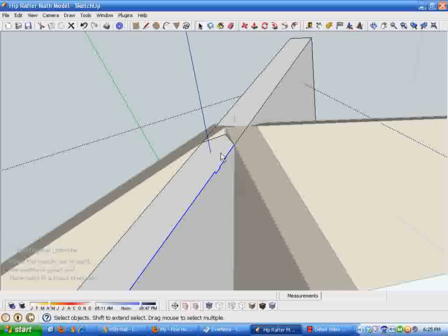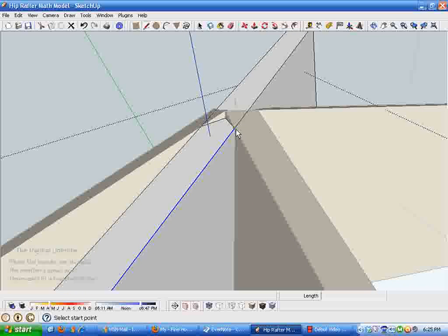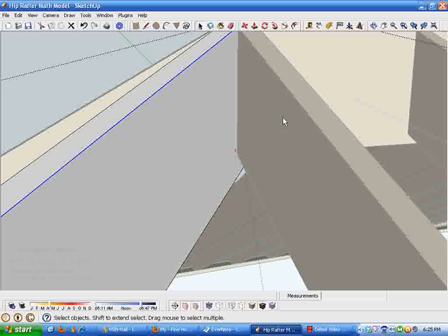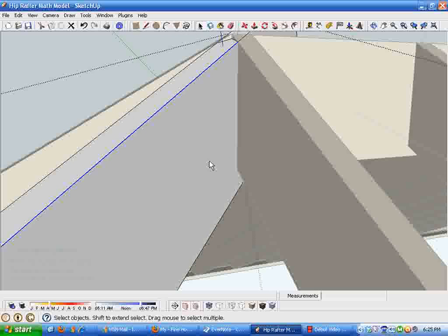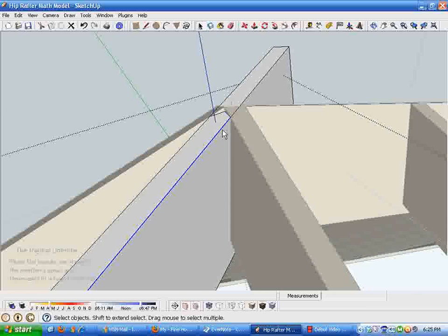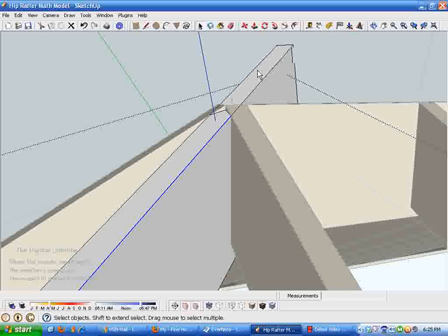And we also are going to need a plumb cut here. So I'm going to get the end point of that line. And as I draw vertically here, that's going to mess things up a little bit, because we pivoted this geometry down, so the axes are misaligned. You can see the blue axis here isn't running straight up and down, it's running perpendicular to our group.